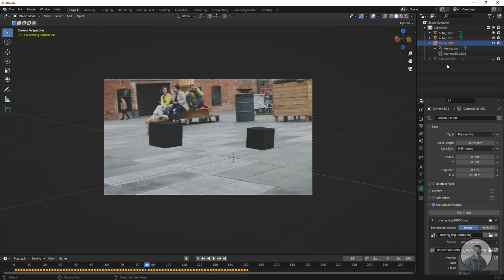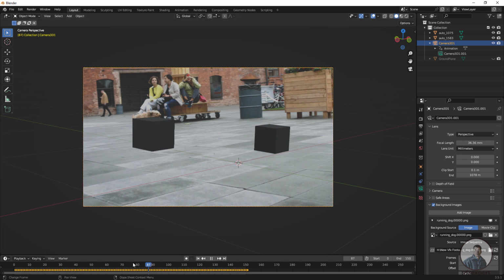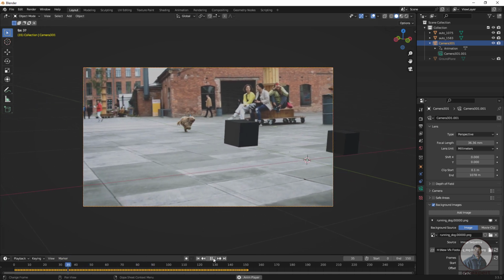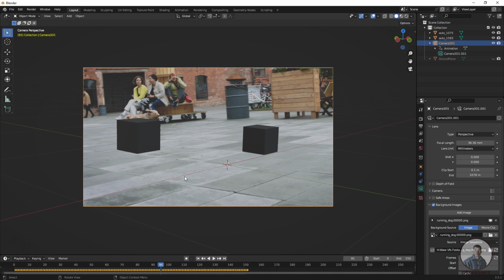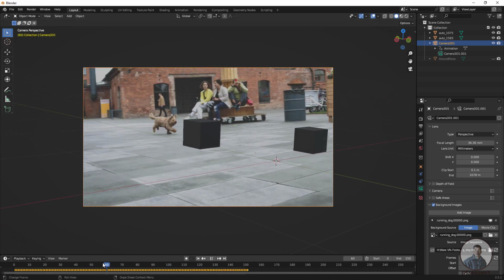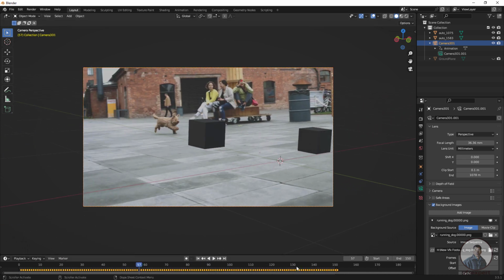Now again we are inside Blender and here I have selected this camera. Then in the object properties or camera properties, type 36.36. So we type the same focal length in the focal length option here. Now if you play and check, all things are matching, and the Fusion camera is imported inside Blender. Also adjust the timeline.